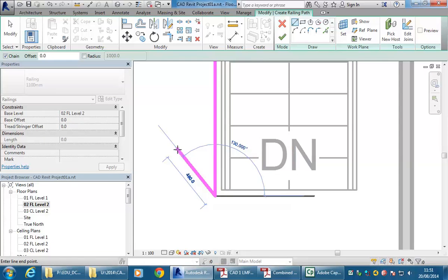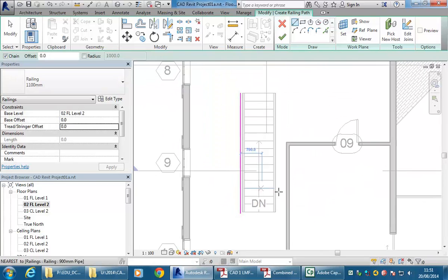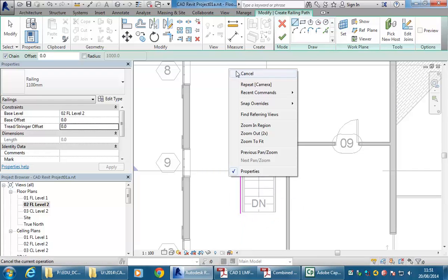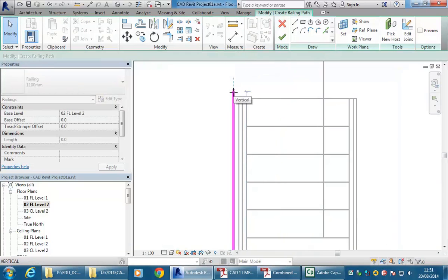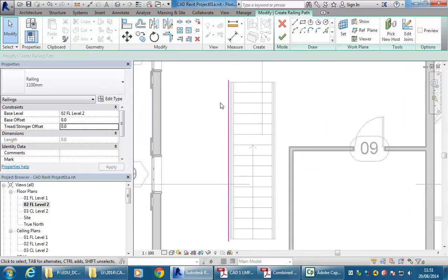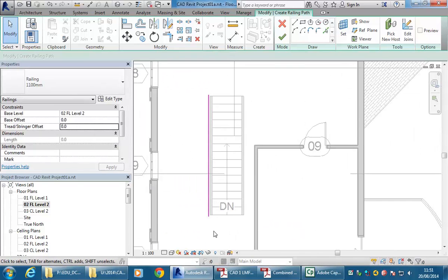Oh no, sorry. Have you had a look at the way stair arrows should be shown? Exactly, up. So when you see it written with down like this, it's American. They're the only ones who do this. Pretty much every other country on the planet, they show just up arrows. So that confused me. So that's the top of my stair, the bottom's there.